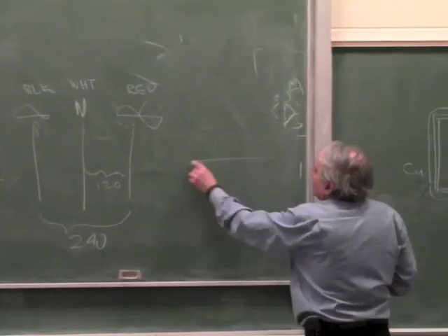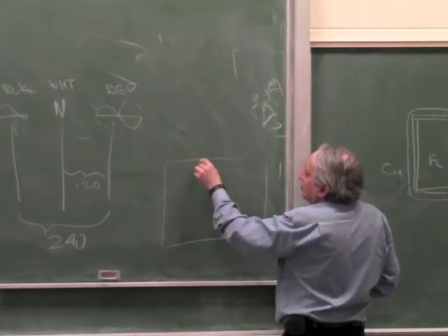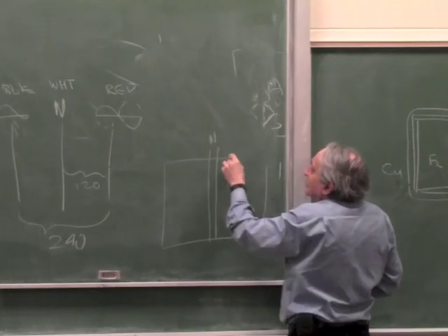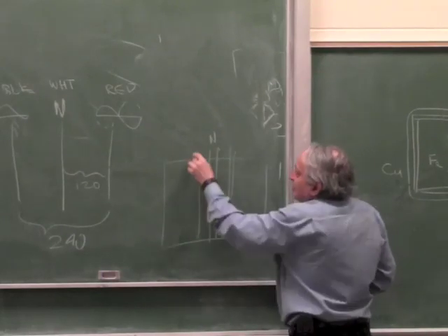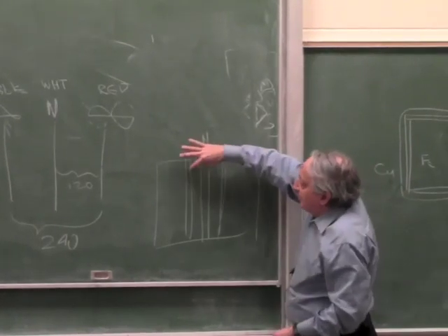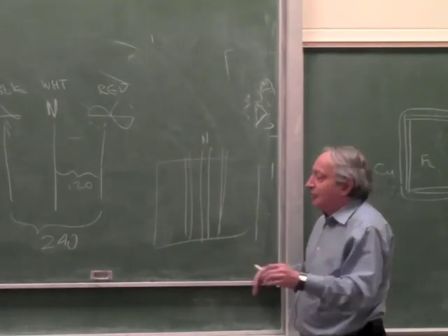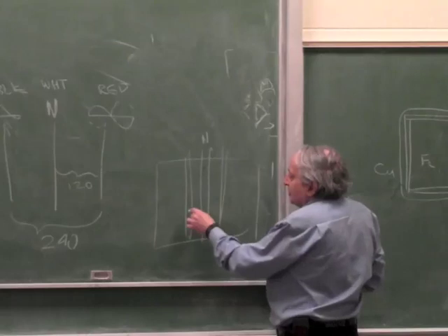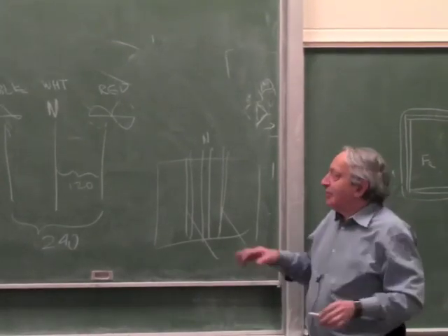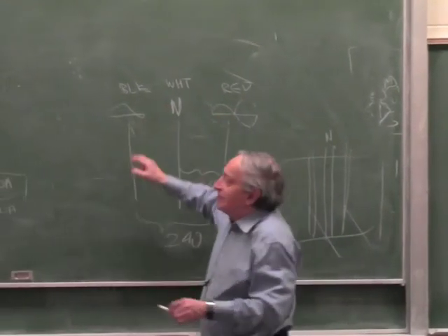If you look inside the breaker box in a house, the way it works, you have two phases. In the middle you have a bar, which is a neutral, and then you have two phases, and the breakers take it alternately. So the first breaker takes neutral to one phase, the second breaker takes neutral to the other phase, to load both equally. If you want 240, like for a kitchen or a dryer, you take it from the two opposing phases.